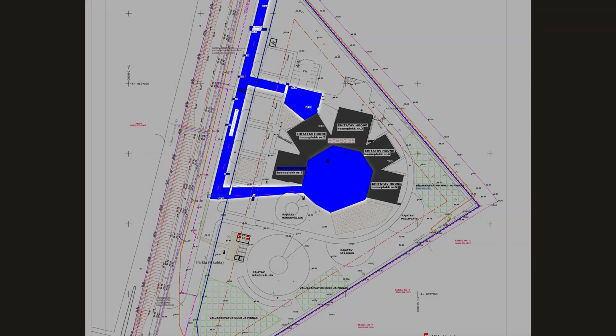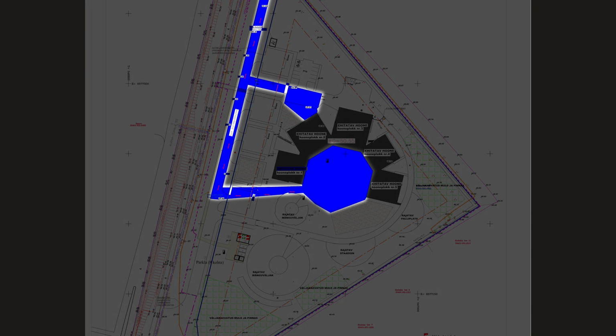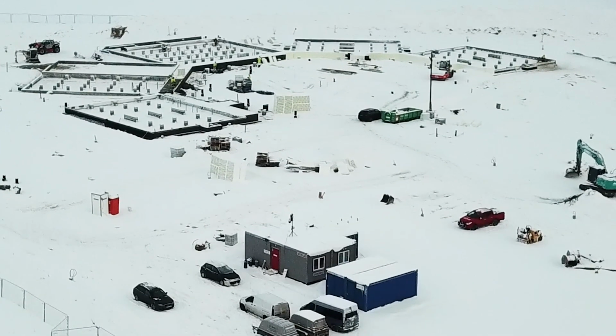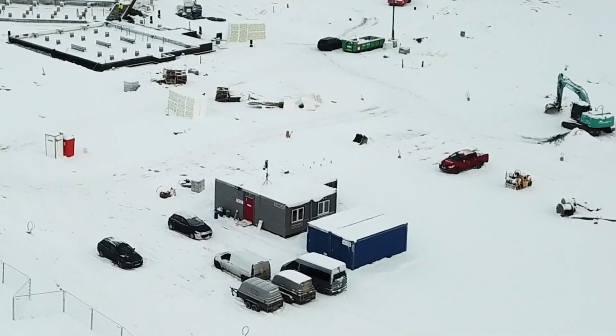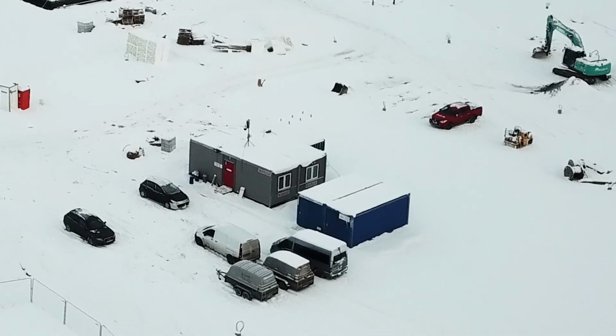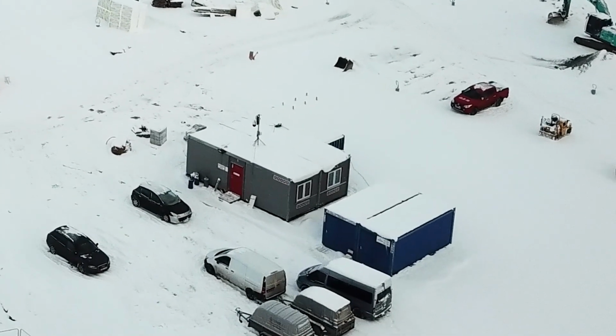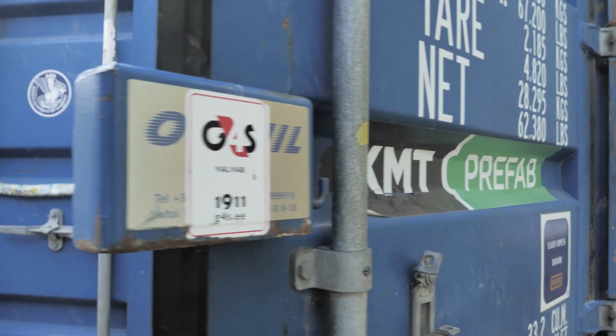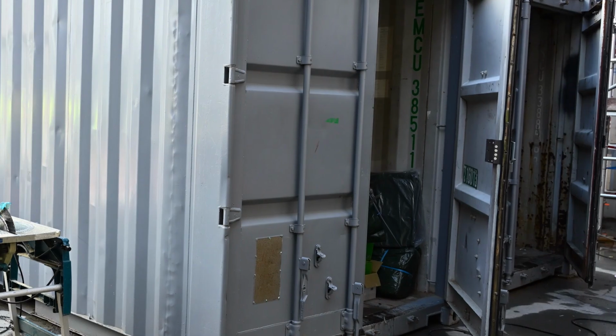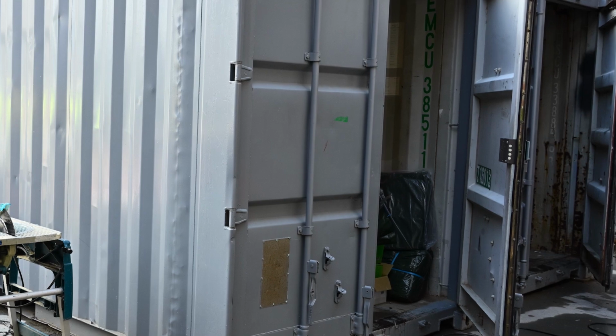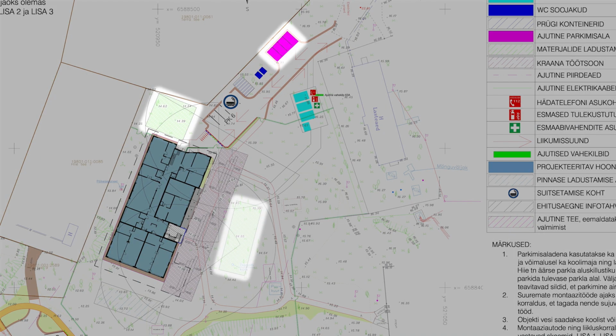The site plan must ensure access for trucks, suitable placement for cranes, and parking spaces for the construction team. These requirements are checked in collaboration with service providers. The site must also have access to electricity and water. Additionally, site offices and secure storage containers with alarm systems are necessary to ensure smooth operations and safety. Storage areas for materials, machinery, and equipment are managed using the just-in-time principle, reducing unnecessary transport on site and ensuring that required materials are available promptly and on time.